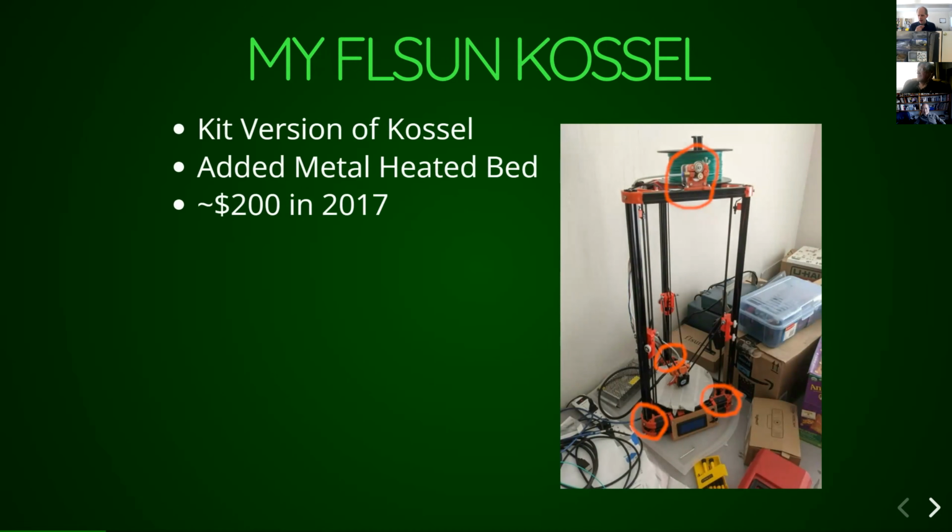There are four stepper motors, three of them in the corners to control movement of the head, and then a fourth for movement of the filament that gets pushed out through the head. They drive a bunch of belts that go up and down the three columns, and those three columns are attached by a little armature to the head. Because the head doesn't have any motors or anything heavy in it, it's able to move quite a bit faster than is typical for a rectilinear printer.